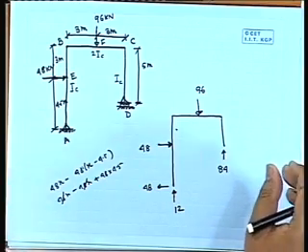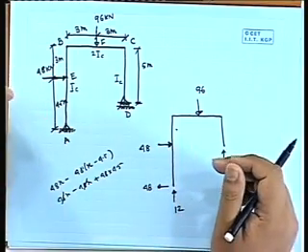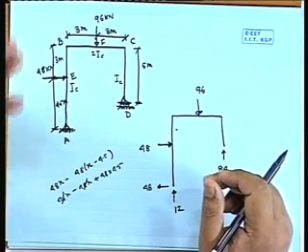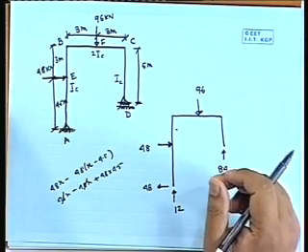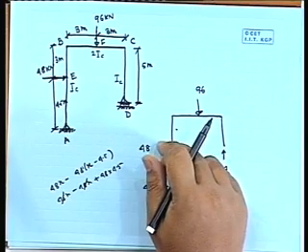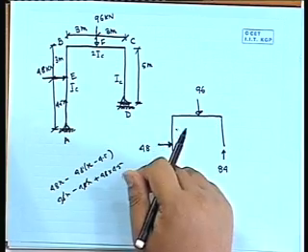Okay. So throughout that portion there will be a constant bending moment, or if there is any doubt you can check it, because if you calculate shear force, here shear force is 48. Once you cross this load, 48 load will be balanced by 48. So shear force 0 means, rate of change of bending moment is shear force. So if it is constant bending moment, its rate of change of that moment is 0. So shear force will automatically be 0.